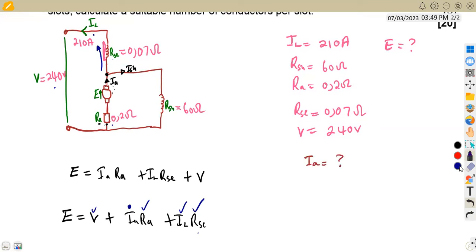All right. So if we take into consideration what I was saying about these currents, the armature current is the supply, the one that is supplying both the shunt and the load current. So it means we are going to have our armature current as the load current plus the shunt current, from our Kirchhoff's laws.